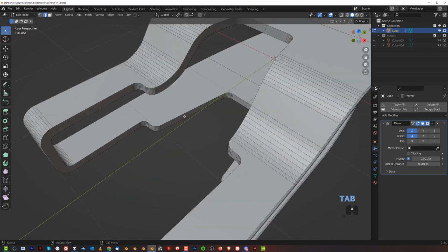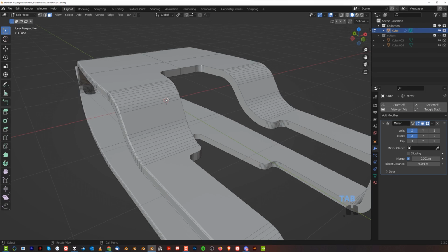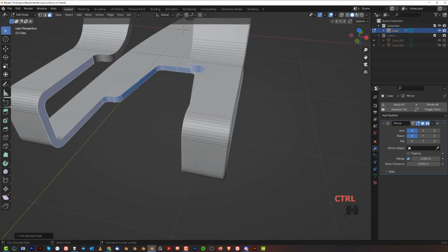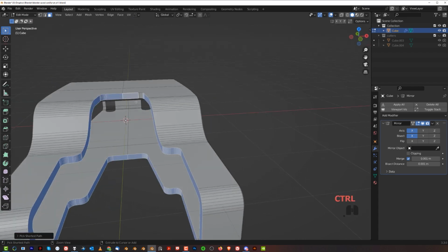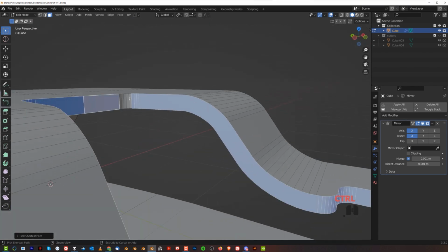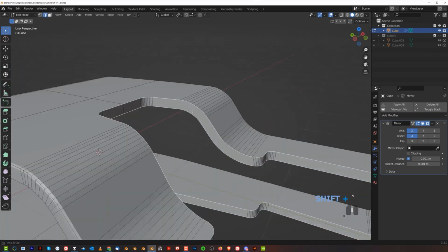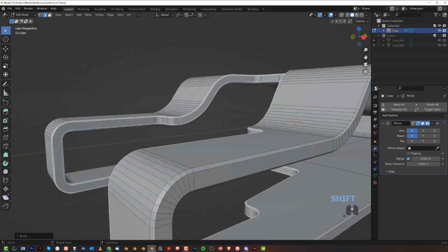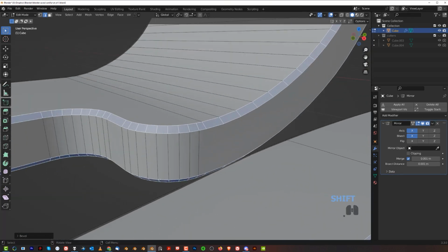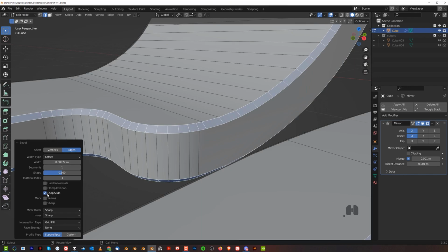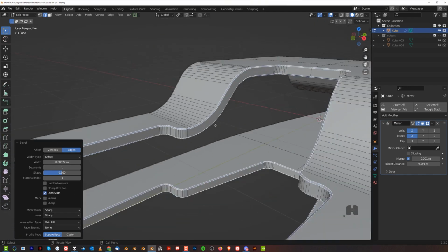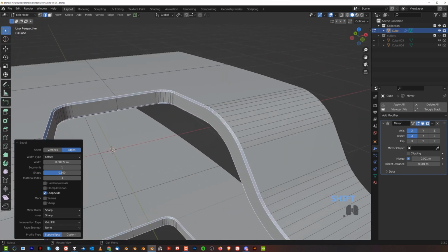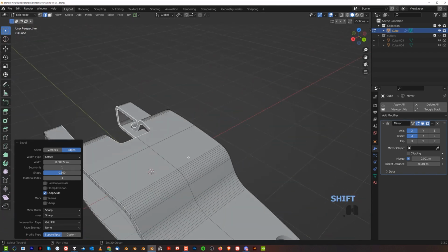Awesome. So let's go here to the middle section. Then we can do the same thing. So let's just select the entire thing with Control, holding Control all around, and here, and then Shift tilde and Control B and chamfer. Now when you create chamfers, sometimes your loop is going to get moved. You can click here and turn off loop slide. You cannot see it here that well, but occasionally the loop is going to slide and you may want to turn it off to create better shading.